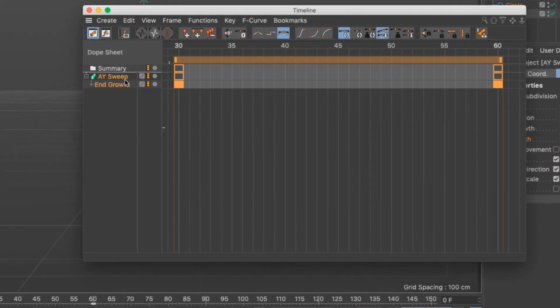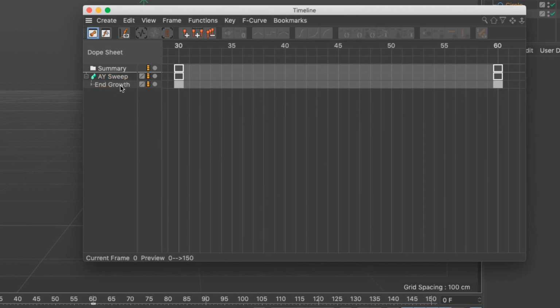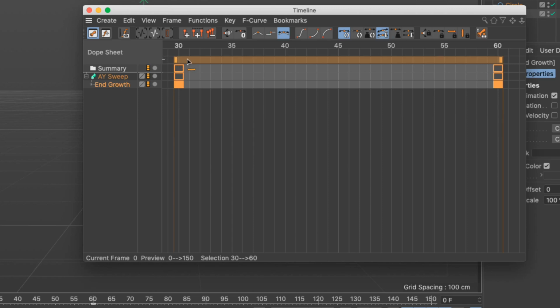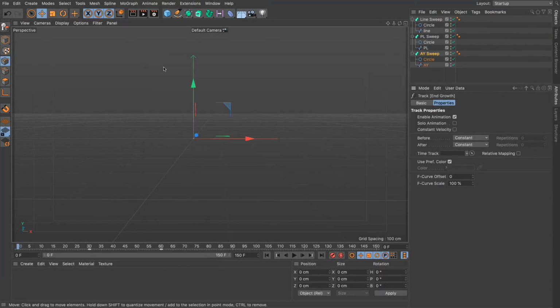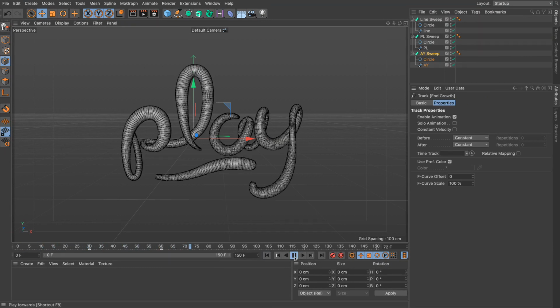And the particular parameter is going to show us the keyframes, the first one which is 0% and the last one which is 100%. With that parameter selected, this orange bar here allows us to either click and drag and change when the animation is going to occur, so we're moving it in time, or go to the ends and you can speed it up or slow it down. And it's as simple as that. Close this and all the changes will take effect. Rewind, press play, let's make sure everything is fine, and I think I'm happy with what I'm seeing.